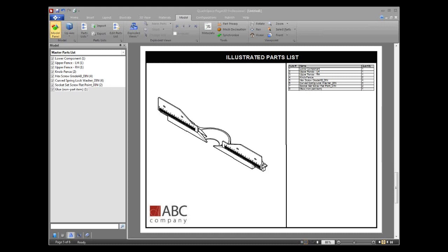In SketchUp, how would subassemblies be established and the respective names, through components or groups or through layers? Using a SolidWorks model and some of the solid-based models, you do get some benefits of a quick and easy way of taking a subassembly, for example, and generating the configurations from that. I suppose that's what you're in reference to on this question. In SketchUp, there's a little less hierarchy built into the 3D design. So in a SketchUp model, there are different components and different layers that can be used, and you can manually group those into your own configurations as defined by you.